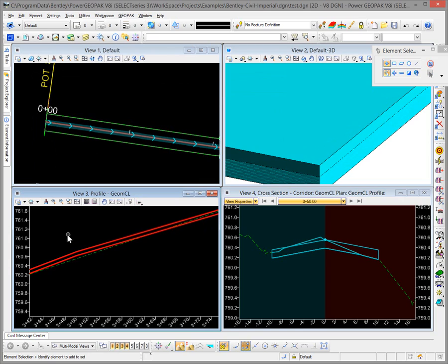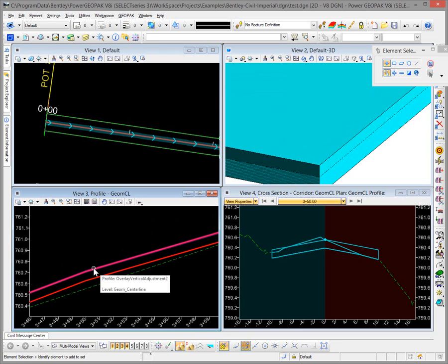And so the last thing is just remember that this profile adjustment tool is literally making a chorded profile, which may or may not be desirable, and you may want to come in and design your own profile using that adjusted profile as a guide. So hopefully this helps you with the understanding of overlay components and also in conjunction with the profile adjustment tool. There's almost an infinite possibility of ways to solve this, but with the power that we give you, I think you'll find that optimizing an overlay job is going to become fairly intuitive after a little practice.